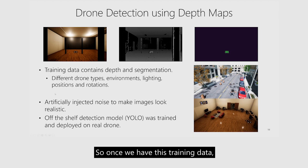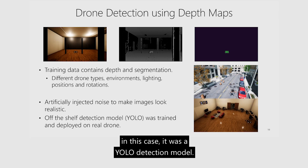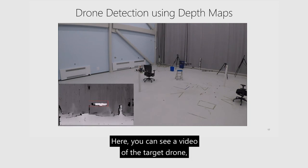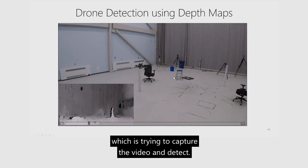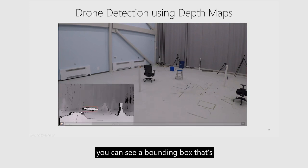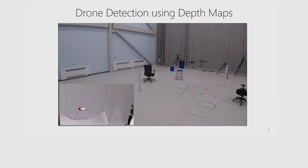Once we have this training data, we were able to train an off-the-shelf detection model. In this case, it was a YOLO detection model. And then we were able to straightforwardly transfer this from simulation to real life. The randomization is the one that helps the most. Here you can see a video of the target drone, the one that's flying here, and then there is the host drone on the left, which is trying to capture the video and detect. As you can see, when I pause the video, there is a bounding box being drawn around the target drone. So it's able to detect and localize it as it goes through flight.